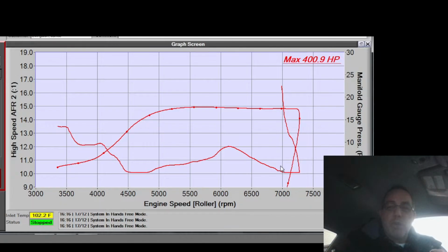So if I've got a really hot spark plug, I'm not creating a secondary ignition event, because that ignition event is still happening at the same spot. But what I could create is a pre-ignition event. I can get it hot enough that now the fuel and air ignite as the piston is traveling up and the pressure is increasing, and have enough residual heat there. I create a pre-ignition event. And so that's the concern with that.